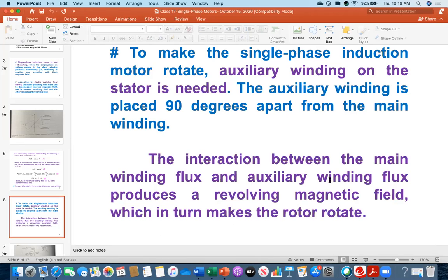And that is the reason if you now open the ceiling fan and see the stator circuit of your ceiling fan, you will definitely notice there are two sets of coil. One is the main coil and the other is the auxiliary coil. And you will notice that in the auxiliary coil, not only an inductor, but also there is a capacitor. Maybe some of you have already noticed inside the ceiling fan the main coil and then the other auxiliary coil plus a capacitor in series with the auxiliary coil. That capacitor is needed to improve the power factor for better, much more noiseless operation.